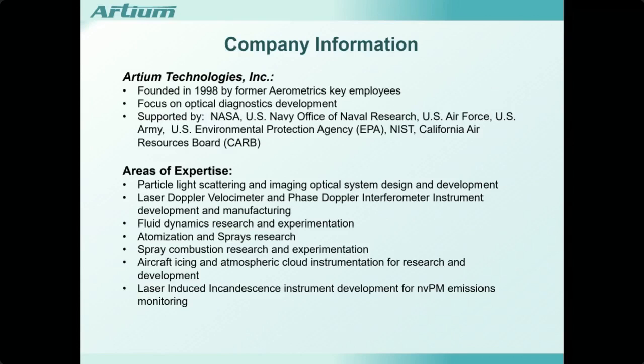We have continued to develop the laser Doppler velocimetry and phase Doppler interferometer methods, which evolved from the basic LDV method. When I was doing my work at NASA, we were concerned about particle response, which I'll spend a good deal of time talking about in this presentation. And the idea was to be able to measure particle size at the same time as the velocity, and that would allow us to discriminate particles that wouldn't track the gas phase turbulence fluctuations. And so that phase Doppler instrument was successful in doing that, but it does a lot more.